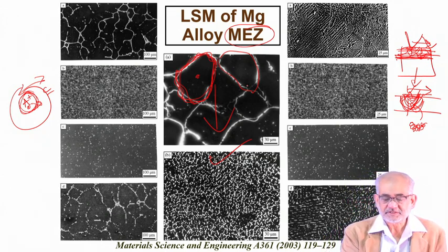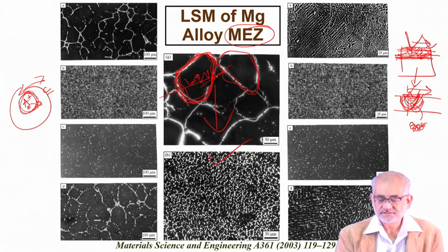Also, this kind of microstructure will mean that these regions will be harder and more wear resistant than the core. So again, during relative motion, these portions will undergo more wear than the grain surfaces. So if, simply by surface melting and rapid solidification following laser surface melting, we can convert this kind of microstructure into an ultrafine microstructure like this, we were able to demonstrate that it gives you a twofold benefit.